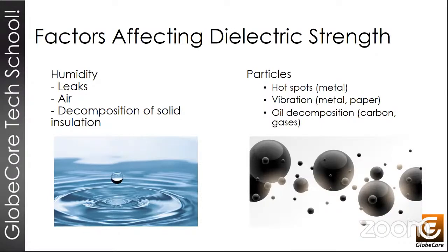So moisture in the oil can come from many sources, and moisture doesn't even need to enter the transformer from the outside, as there are actually internal processes that cause formation of water. Leak points are the main factor responsible for the increase in humidity in the transformer. However, there are also transformers with breathers, and those breathers tend to be a kind of weak point if due care is not taken in their maintenance. So a timely change of silica gel and continuous monitoring of moisture levels, as well as alternative moisture extraction equipment, are all important to keep moisture levels low in the transformer oil.